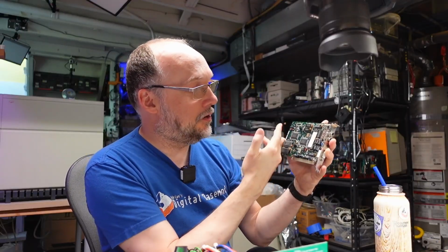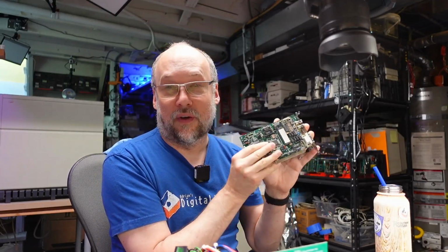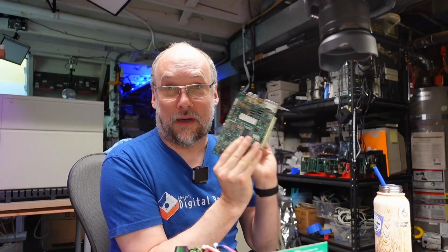And that also made me realize that if I turn off the system here, the reason why this VTEC card does not flash, even with the stock routines, is because it just ignores that bit 3 entirely. Or if that signal is available on these ASICs, it's not actually hooked up in a way that would disable the outputs. There are several jumpers on here that do all sorts of things, and maybe one of those jumpers actually re-enables that feature. I'm not totally sure. But definitely this card is just ignoring that bit 3 entirely.